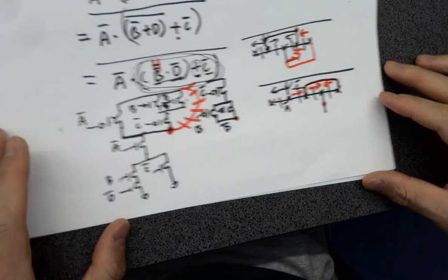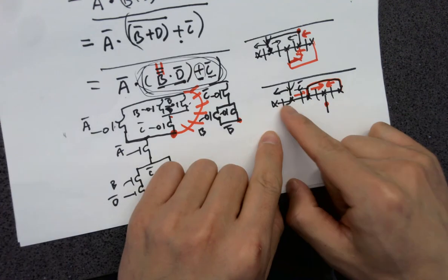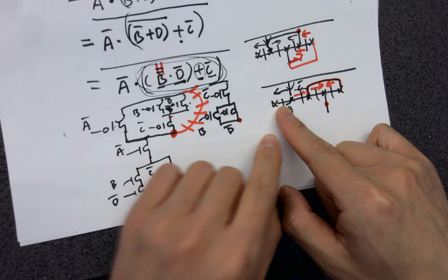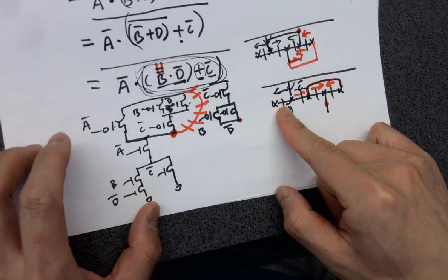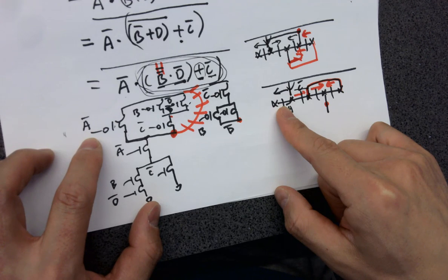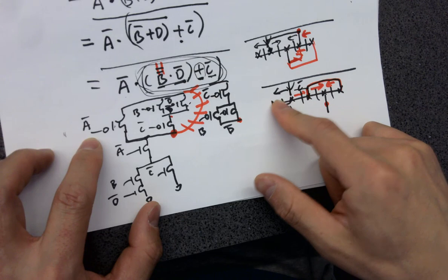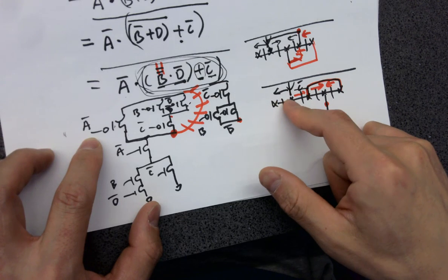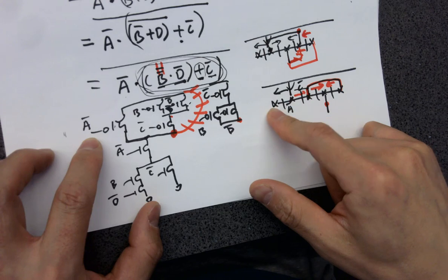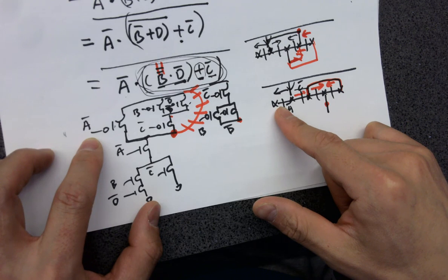could you point to where the gates are on the stick diagram? The gates are the little stick in the middle. Correspond to the actual diagram. It's like the gate is the line. Yeah, this line is a gate. That's a diffusion. That's a channel. Yeah, the drain and the source, drain and source, yes. So then wouldn't the VDD have to go on the other side of the A gate because VDD isn't going to C at all?